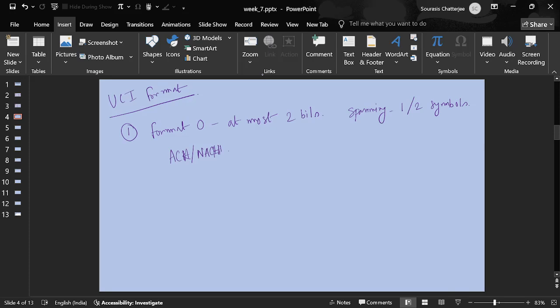So if it's about ACK and NACK, how are they transmitted? Are they transmitted in their raw form, like 1 bit to 1 bit mapping, or is there some robust way of doing it, adding some parity bits and all that? Yeah, I think 1 bit is converted to 12 bits and then we send it like this. Okay, so let's say 1 bit to 12 bit conversion.